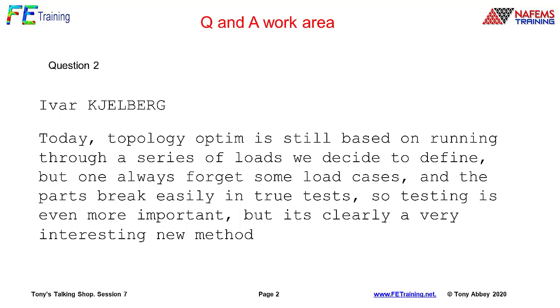Yes, I emphasize I'm just dipping into this big subject. One of the things I always say is that if you forget to define a load case in topology optimization or any form of optimization, you pretty well just design a structure which is guaranteed to break. And what you're extending that to, Ivor, is to say we also need tests to make sure that the way we describe the loading in the analysis side, the virtual loading, is adequate to define the real world. But at its simplest level, if we leave off a load case, then we're in serious trouble.